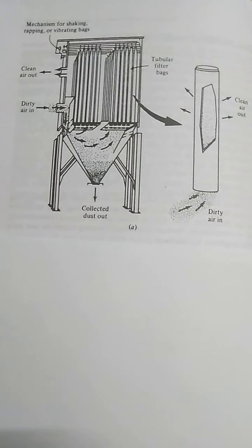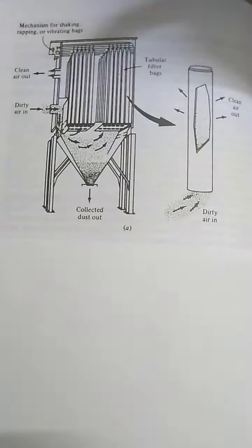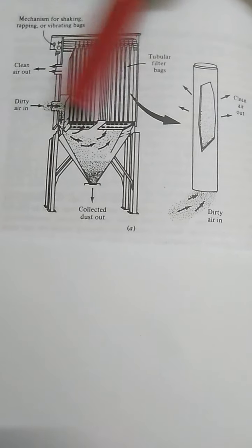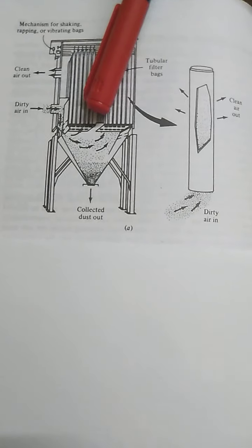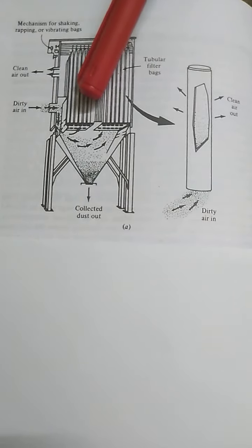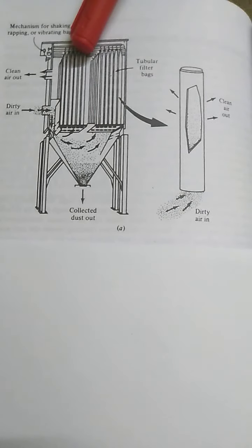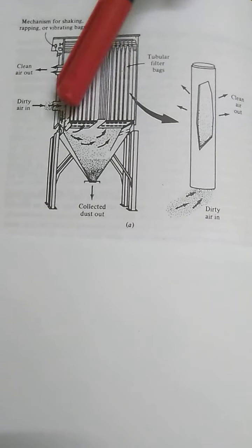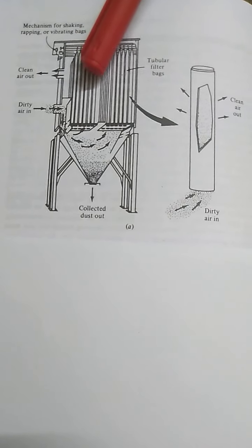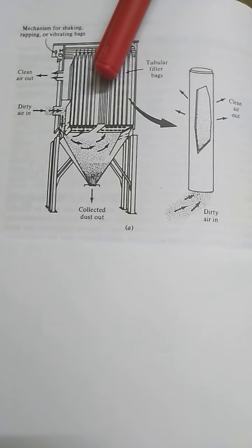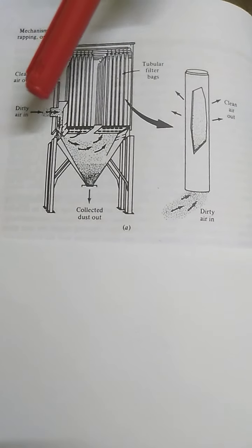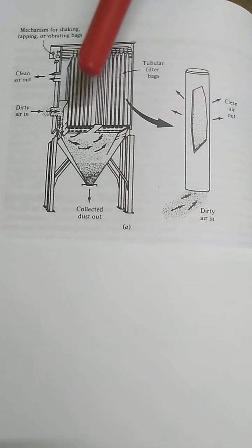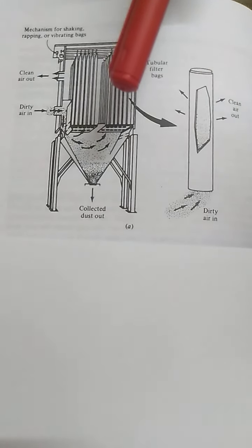And efficiency during the pre-coat formation, that means when we enter the fresh air after cleaning, if we enter the fresh air inside these fabrics, at that point the efficiency of suspended particulate matter removal will be very much higher, because the pores are clean and do not have any suspended particles in them. As we enter the suspended particles inside it, since the pores are open, they are getting arrested.